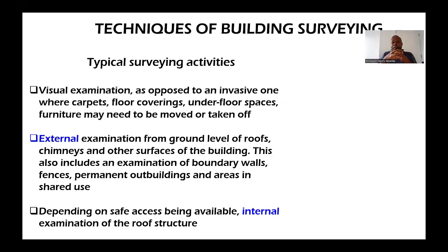Now, typical surveying activities. Remember, we did say in one of the earlier slides that it involves intensive inspection. So the kind of activities involved in surveying are visual examination as opposed to invasive examination, where things like carpets or floors or underfloor spacings, furniture may need to be moved or taken up. So visual examination. External examination from ground level of roofs, chimneys and other surfaces. The key word there is external examination.